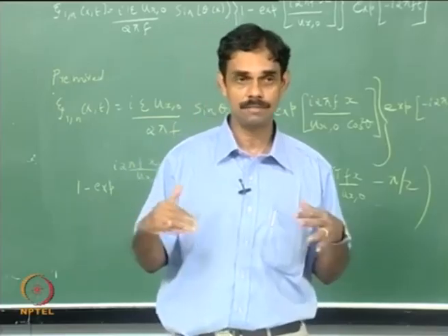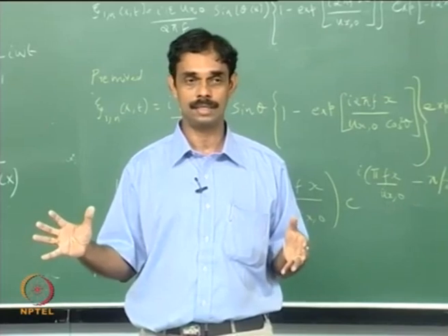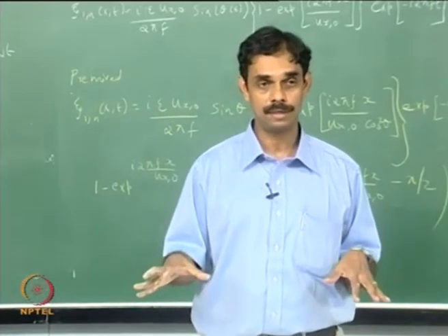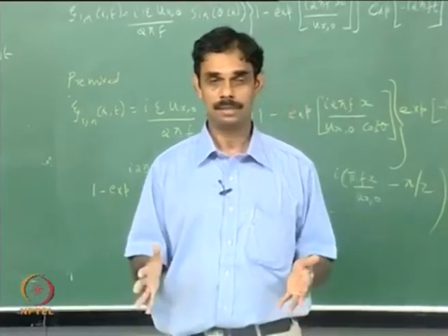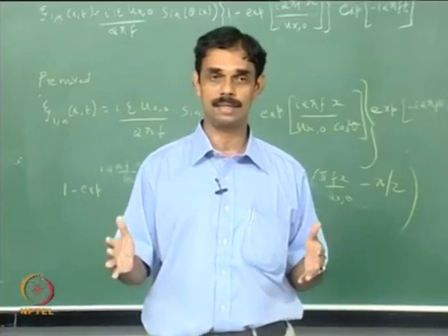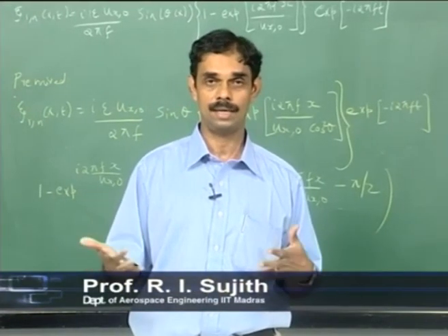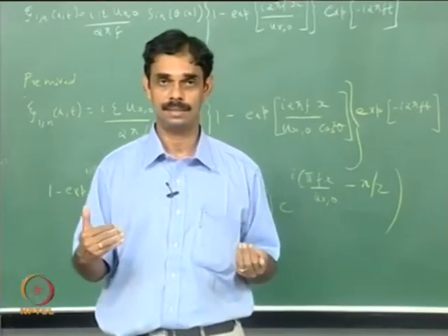For each situation you can construct a model for the unsteady heat release rate, then plug it into the corresponding wave equation and solve in whichever way you prefer. I hope you will be able to extend all this analysis to your thermoacoustic system and analyze what happens to it, both the linear stability and the nonlinear stability analysis. Thank you.